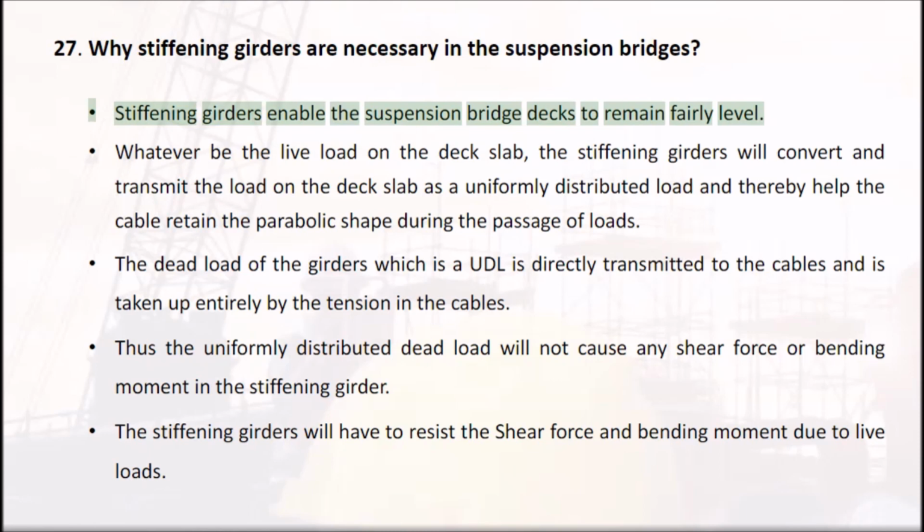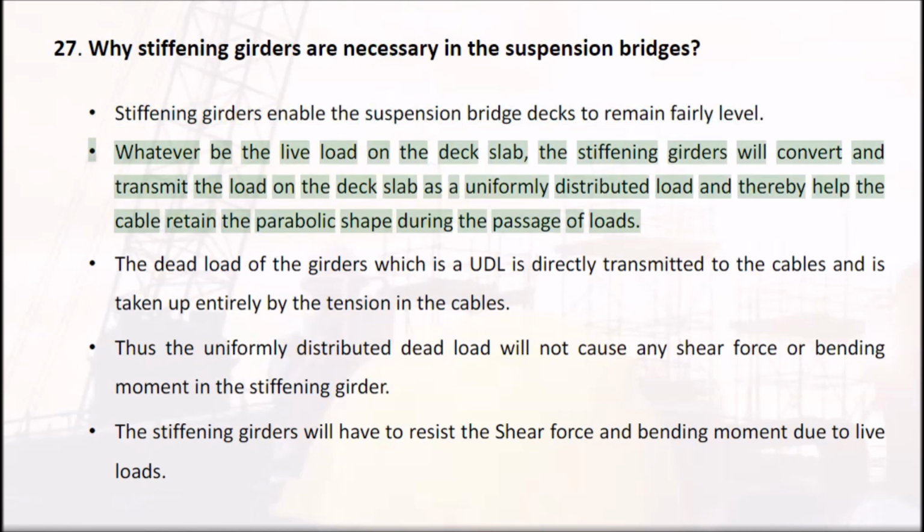Stiffening girders enable the suspension bridge decks to remain fairly level. Whatever be the live load on the deck slab, the stiffening girders will convert and transmit the load on the deck slab as a uniformly distributed load and thereby help the cable retain the parabolic shape during the passage of loads.